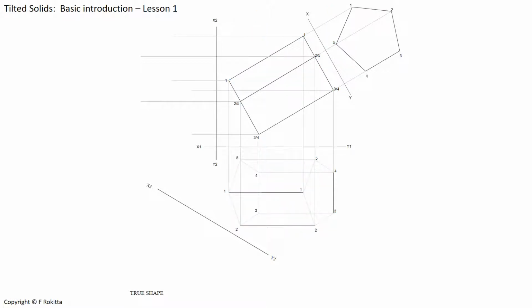Here we have now drawn in some of the outlines of our top view with solid lines. We will make sure that these lines are drawn neat and accurate using the correct pencil. Once we have completed drawing the outlines of our top view solid, we need to determine which parts of our prism will be hidden. Therefore, we need to move back to our front view and observe the front view from the top. If we do this, we will notice that the base of our prism is not visible if we were to look down on the front view.